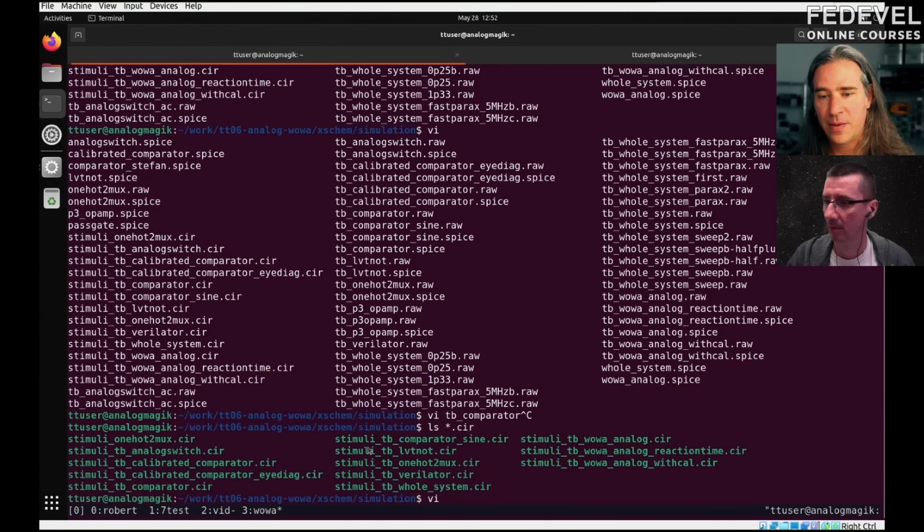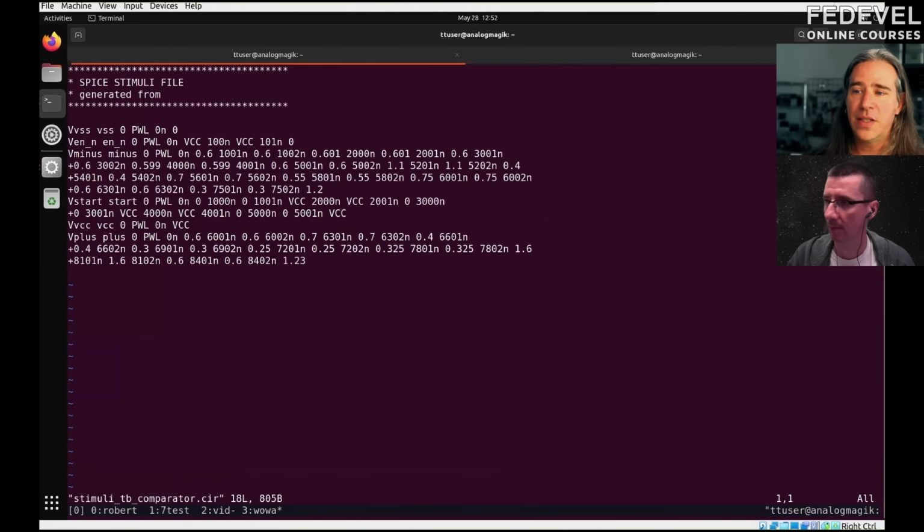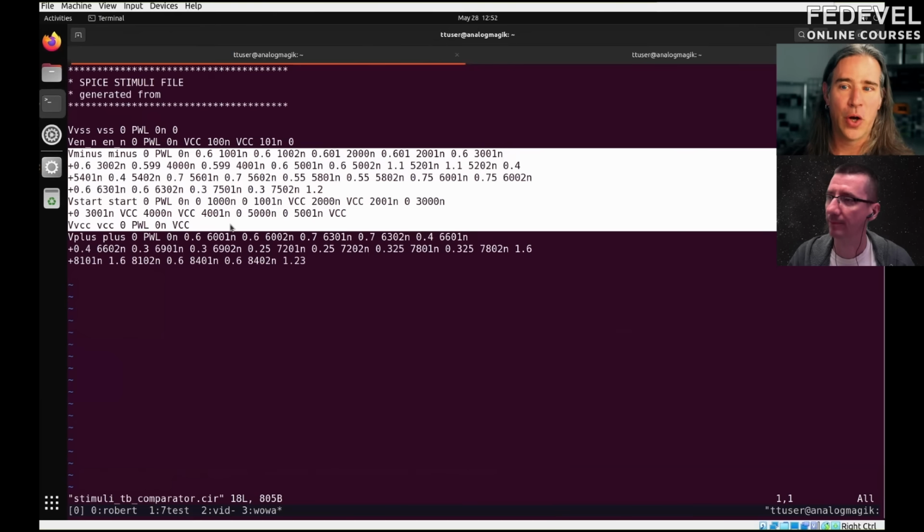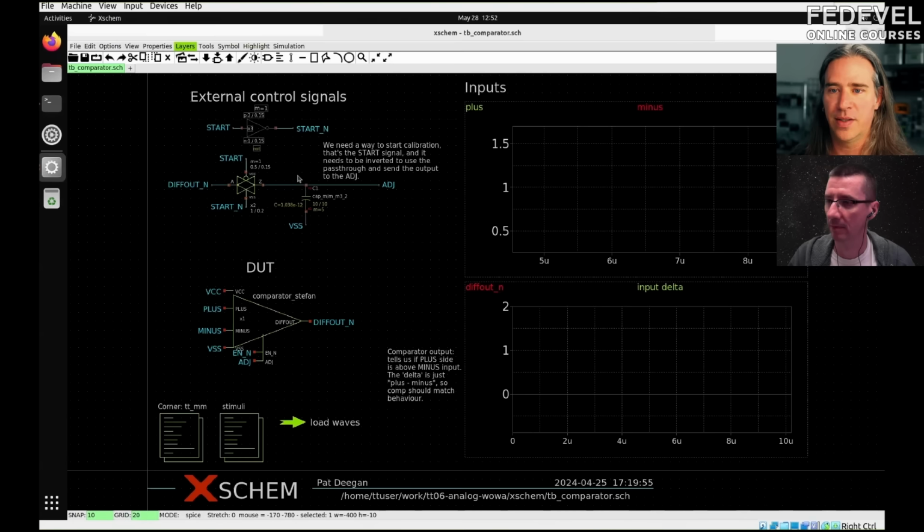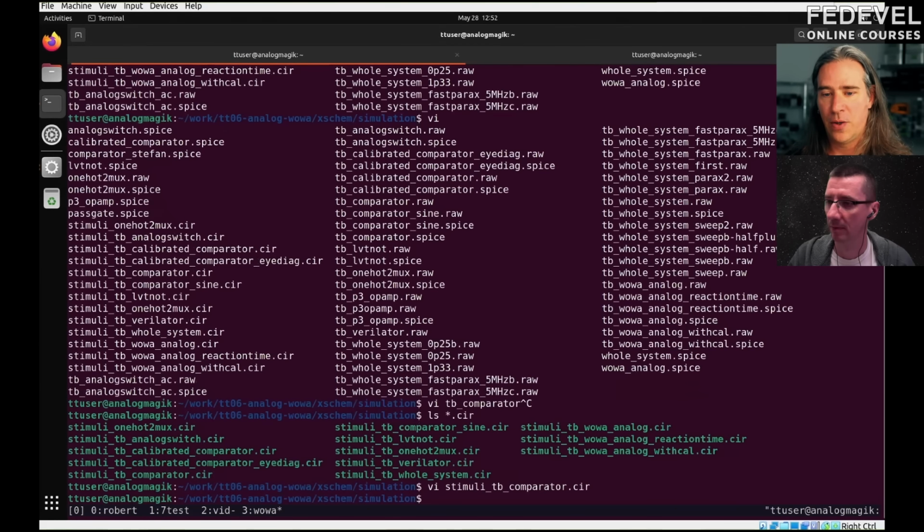Okay, this guy. Stimuli, TB, comparator, SIR. So this spits out Spice, which is these V, and okay, you don't really have to care about this. I'm just showing you that you set these commands and you say, set the signal high, set the signal low, and it'll just deal with that for you. And it's much better than trying to do this in Spice.